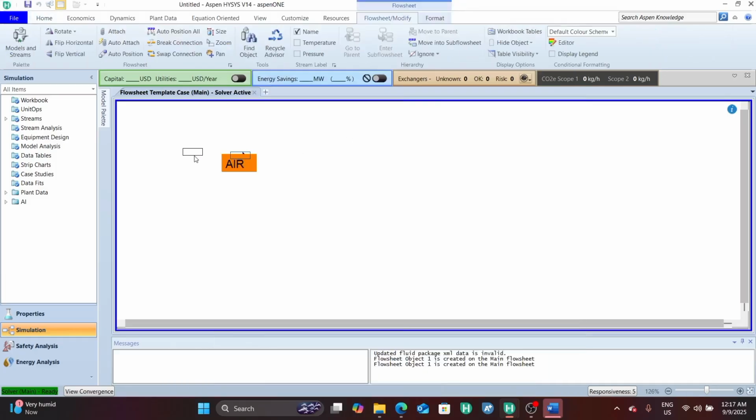It's to be expected. Now, the next thing is that we need to carry out three-stage compression and intercooling and get our vapor fraction down to 0.45 or less. To do that, we definitely know that we need to drop the vapor fraction, and what drops the vapor fraction for gases is basically cooling, and that's the reason why we have intercooling in between. Cryogenic distillation is all about carrying out separation of the mixture at very, very low temperatures.